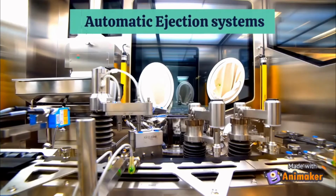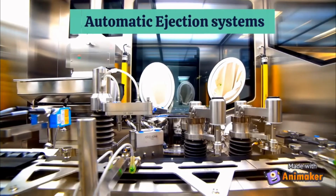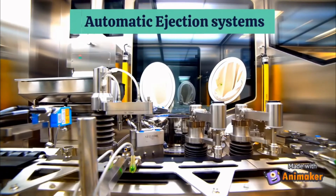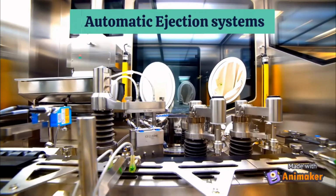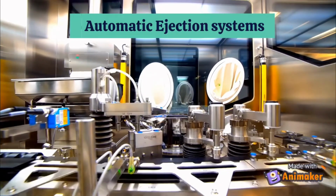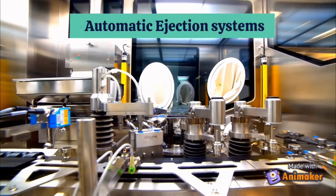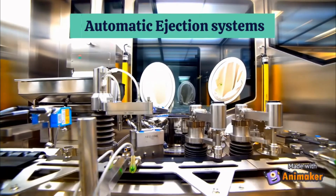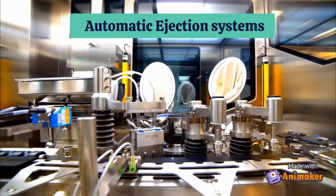Thirdly, automatic ejection systems eject the work pneumatically or mechanically. The advantage of either approach is that operators don't have to reach into the danger zone to retrieve workpieces. However, these systems are restricted to use with relatively small stock. Potential hazards include long chips and noise.